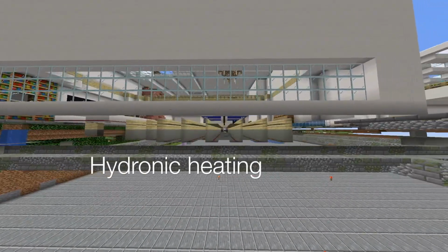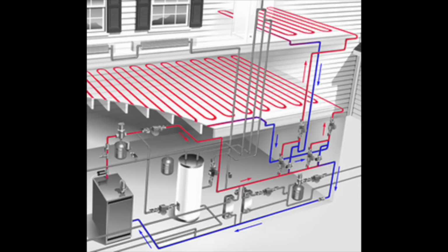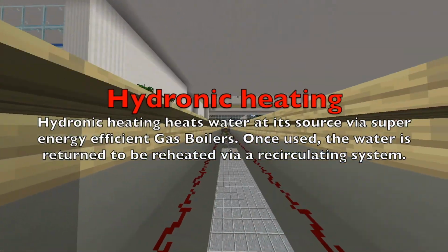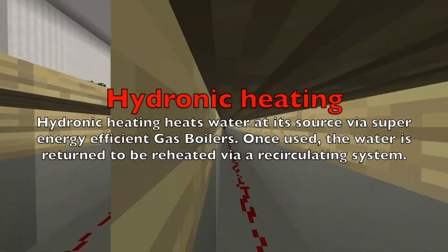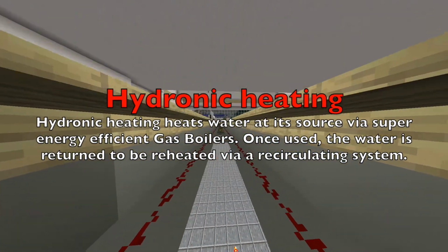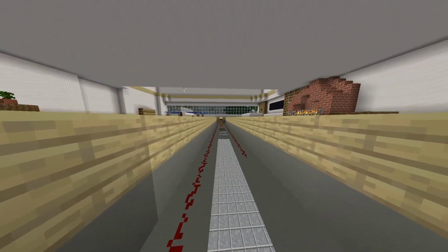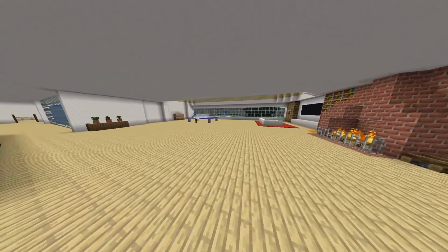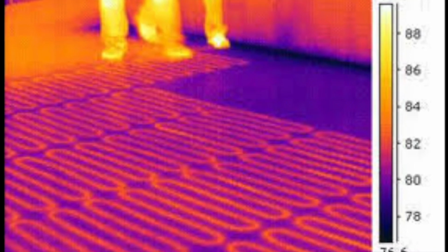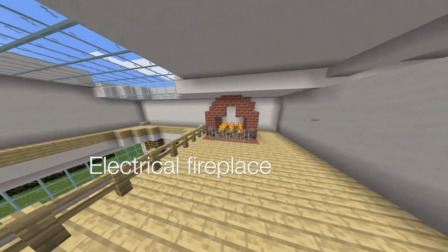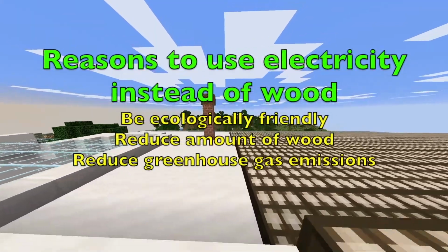The concrete slab floor heating and geothermal heat pump system work similarly, by heating the floor through hydronic heating, which is when warm water runs through the tubes underneath or within the flooring. A substitution for the water can be electrical heating, in which electric wire elements are laid within the flooring. This is a source of convection heating for your body and conduction for your feet. The electrical fireplace works as a source of direct heat.